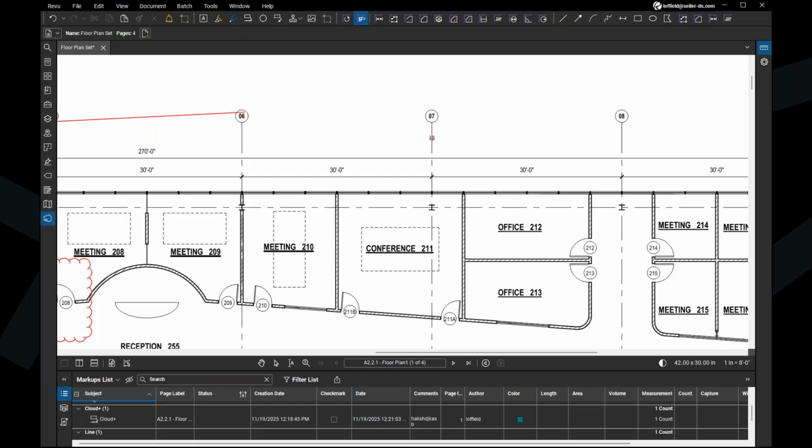So I'm just going to select this little bit of line work here, and I'm going to want to draw a straight line as straight as possible. That can be kind of hard to do, depending on how much coffee you've had or something. But if you hold the shift key, it doesn't matter where your cursor lies, it's going to allow you to draw a straight line. So just remember, hold that shift key in.